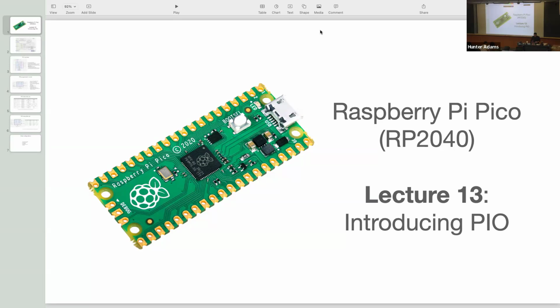So what I would like to start doing, the piece of Lab 2 that we have yet to discuss, and that I feel like it's important that we do discuss, is the VGA driver that you are all using. The reason that I think it's important is your goal in this lab is to get as many balls falling through that Galton board as you can. One of the things that you'll definitely want to do is overclock the processor, which on the RP2040 the SDK makes incredibly easy, and ultimately I'll show you how to do that.